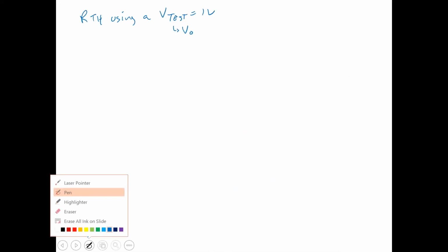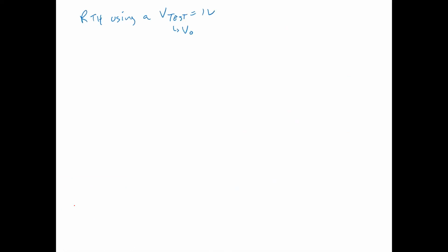Labeling it VT can be confusing because T is the same T as in Thevenin. VTH is the Thevenin voltage, VT might be your test source, but you have to be really careful not to mix those up, right? So VO is good, but you can call it a test voltage as well. You're just hooking up something to it to see what it requires for voltage and current.